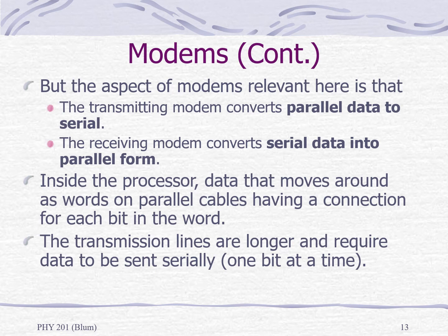And then when we are going to send the information out to some longer distance on some kind of transmission line, we're going to have to convert the data from a parallel form to a serial form to be sent over the wire. And then as we are receiving the information, we're going to have to bring the information in serial, 1 bit at a time, and then convert it into a parallel form.